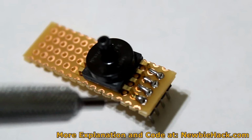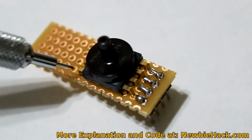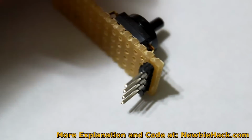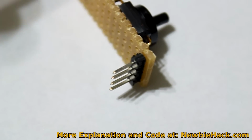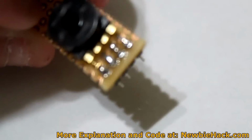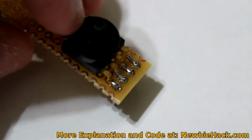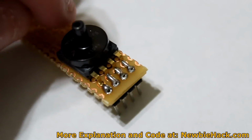I took the only 4 leads that we're going to be using. We're not going to be using 5 through 8, we're only going to be using 1 through 4. And I put it on the perf board, and on the underside, I have a header to make it a lot easier to plug into the prototyping board, the breadboard. You can actually plug the SMD leads inside the breadboard, but it's really difficult to get a good signal out of them, and you have to keep moving them and jiggling them to get a good signal.